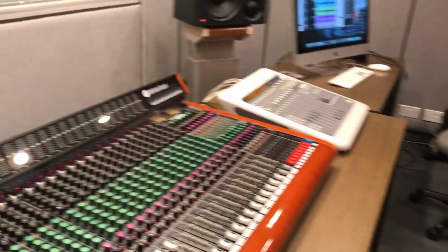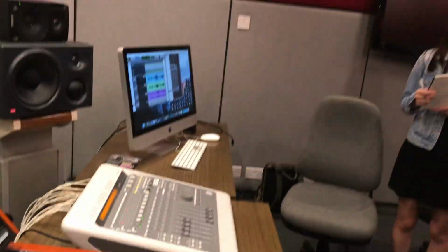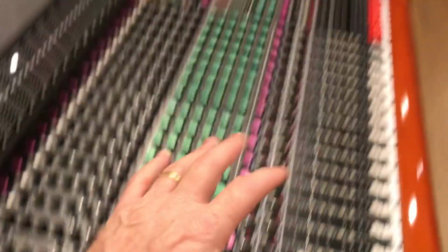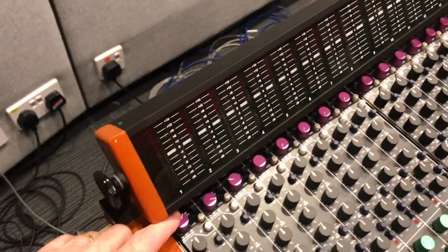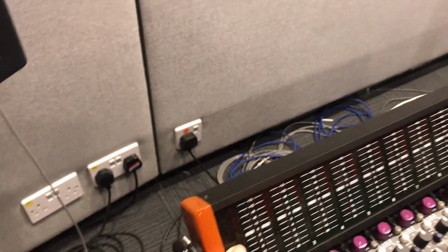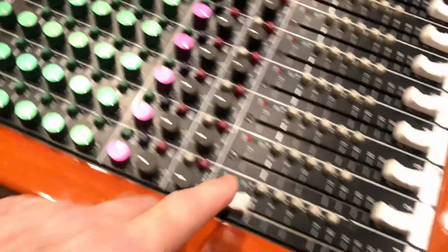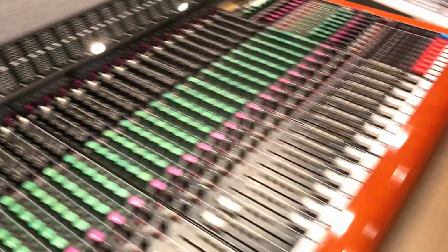So what we're trying to do is balance what is referred to as the signal to noise ratio of this mixer. That's why we need to ensure that the gain input is optimized according to the input level. With the fader at 0, optimize the gain input, have this fluctuating around 0.